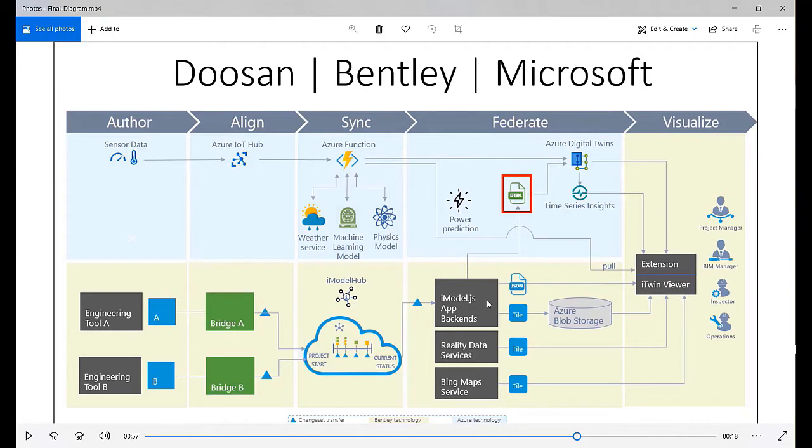And we can look at, so we have 10 turbines within the iTwin, and they have some custom properties that might lend value into our ADT instance. So we port those properties and different instances of the turbines over into our DTDL, and we use that to generate our ADT instance. So both these models are in sync. The Azure Digital Twins and your iTwin, they correspond to each other, one-to-one. Okay, so this finally gives us the ability to start getting data from the Azure function into our ADT instance.